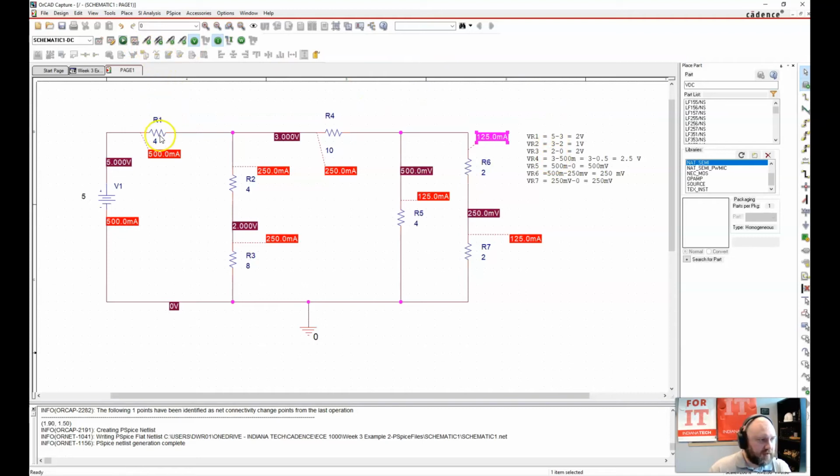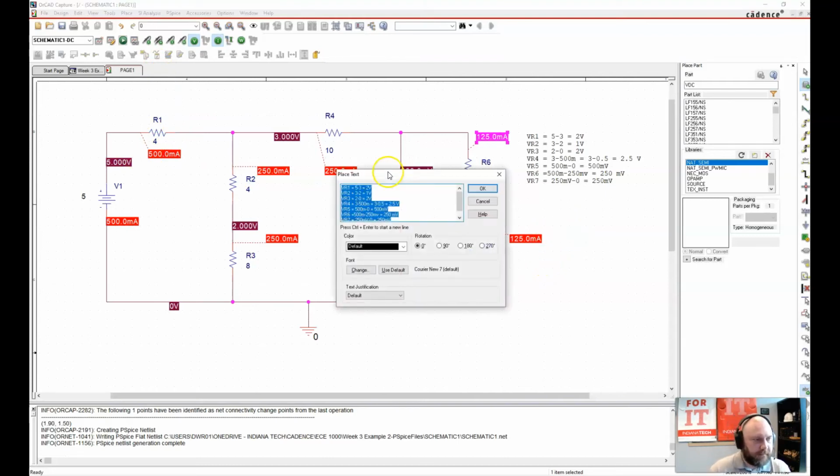So to verify that this should be 500 milliamps, for instance, I would have the voltage drop across R1, so I'll have the current for IR1. And I do want to see a computation for this, because otherwise you just turn the simulation on and you can see that it works. I want to see, okay, well, it's 2 volts, and then you can rearrange the equation in your head, because it'd be 2 volts divided by my resistance to get me current.